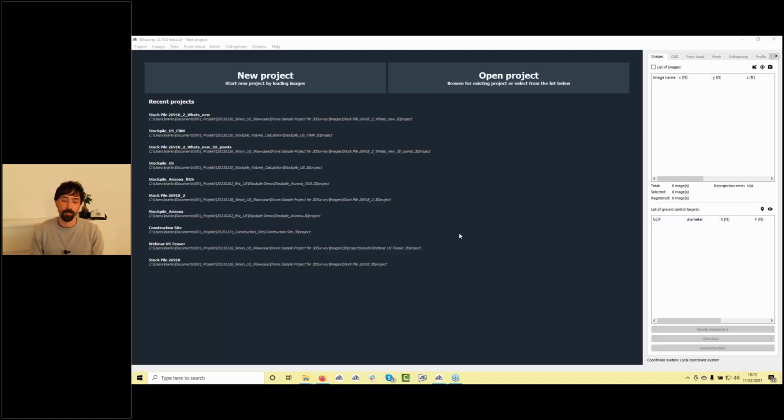I know the P1 has just more megapixels, but if you fly up to 100 meters, you don't need them, okay? With the Phantom 4 RTK at 80 meter height, you get a resolution of 2 centimeters, and this is more than enough in most cases. If you like to have better accuracy, you can fly lower.